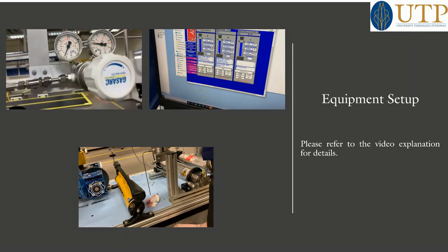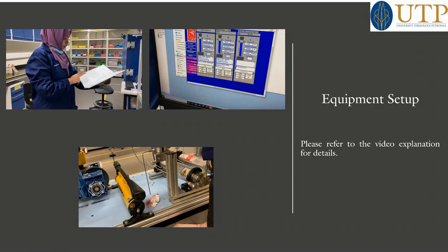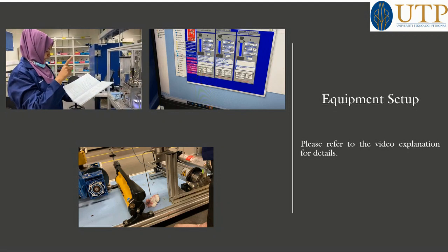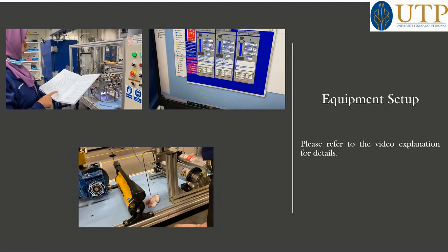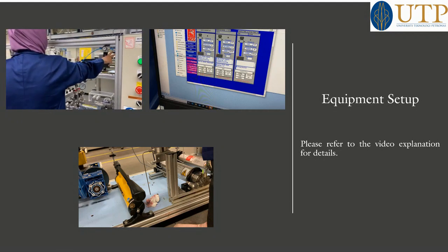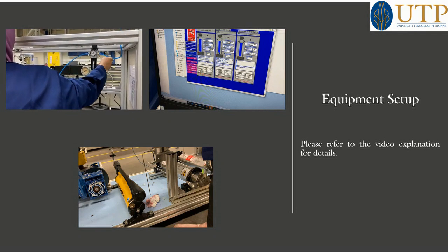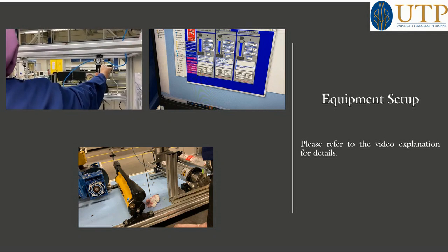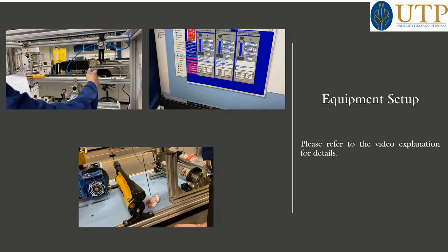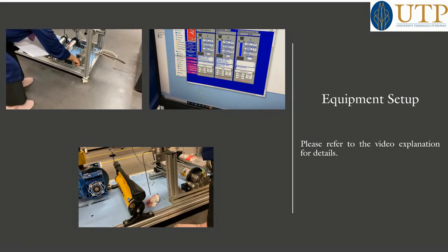So after that, what they say: regulate valve from the lab and set. Okay, I already regulated it and set it. Then select the valve towards carbon dioxide. So this valve, I already talked about this one. This one already, the direction is towards carbon dioxide. So then select the valve. Okay, open V20 first to release the inside gas. This is our V20. So I'm opening this one, to release the inside gas.